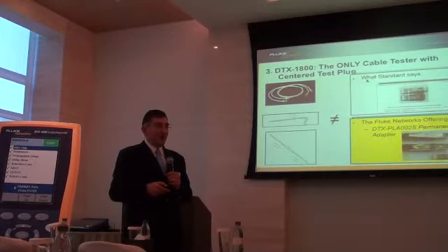We don't certify for 1 meg or 10 meg. We don't even certify for that. We do not certify for the application. We certify based on the cabling standard, which is a lot more stringent than the application standard. They're 10 times more stringent. Something that fails on Cat6 might easily pass for 1 gig, but that doesn't guarantee that things will work. It's not future-proof. There are two separate things. Application standards are separate from the cabling standards. Cabling standards are a lot more stringent.